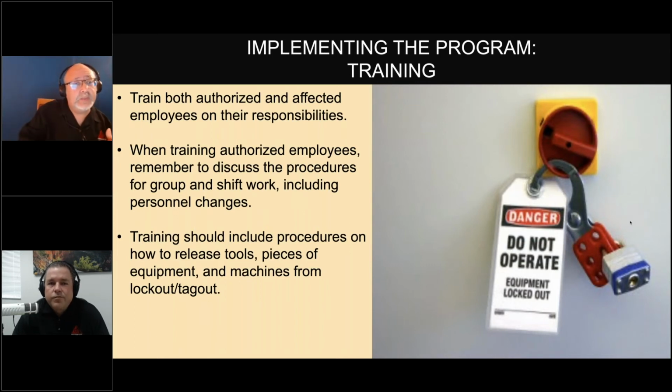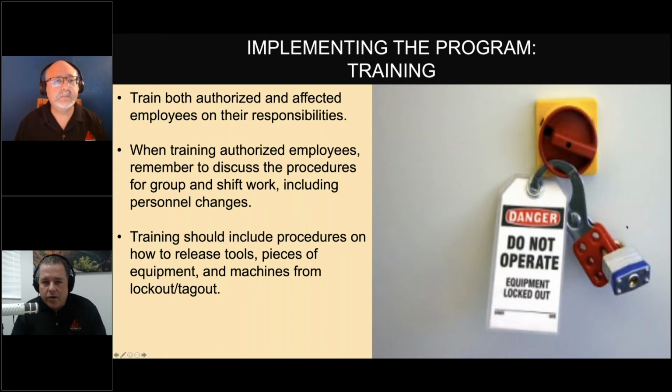And the responsibilities of the affected individuals, now their responsibilities would be what? To pay attention, and to follow the procedures. Yeah, and it would look like this: an authorized employee would have a problem with the machine, or a maintenance guy was going to bring it down to do some cleaning or servicing, and he would announce to everybody in the vicinity, hey, this machine's going down, and I need to do some cleaning, so it's going to be locked out and tagged out.